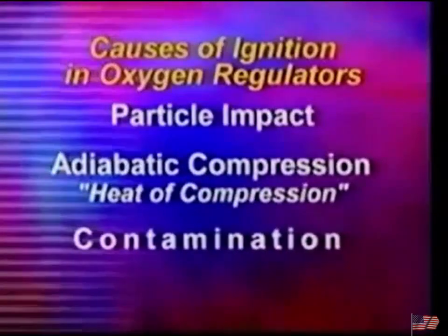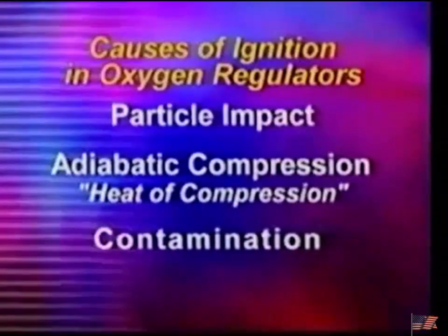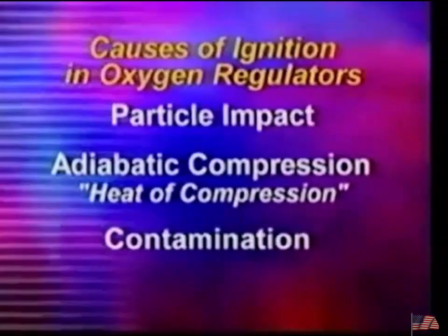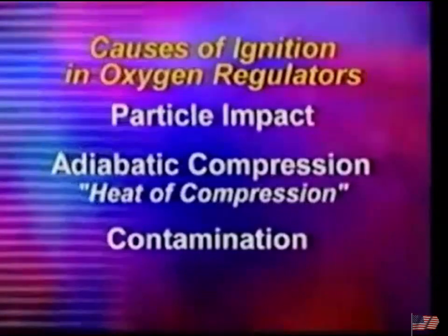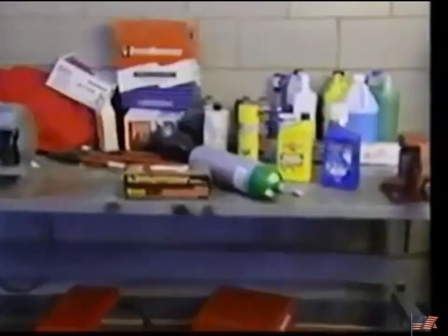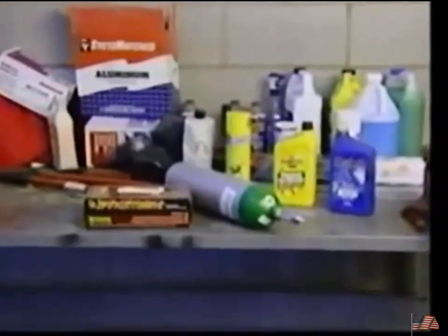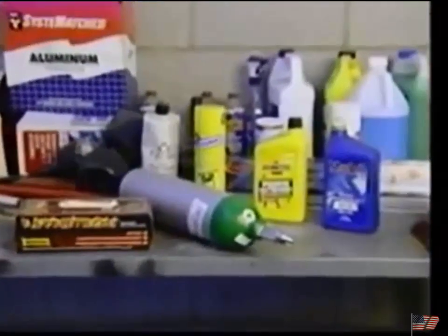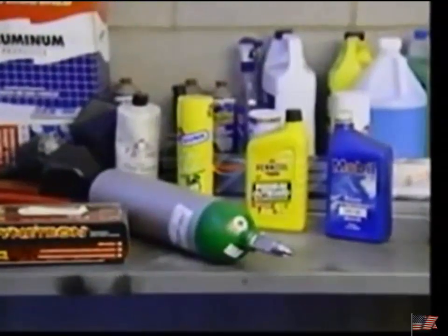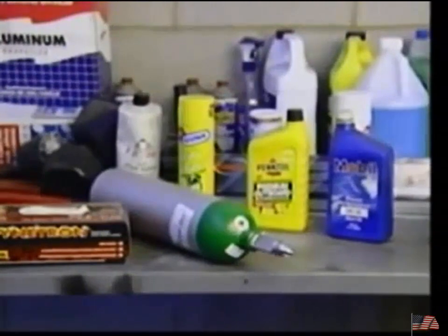contamination. Now this involves exposing parts of a regulator or a cylinder to a contaminant like grease or an oil-based lubricant, parts that come into contact with the high-pressure oxygen. Those contaminants are very easy to ignite either by particle impact or adiabatic compression.